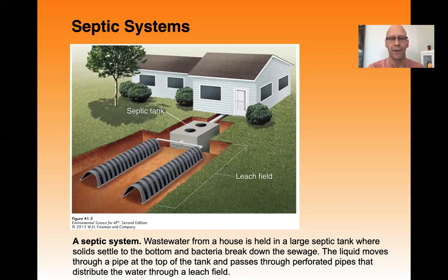And the bacteria that are in your soil are the consumers of any organic waste that's in your home sewage. And that bacteria can process that waste, and as that water infiltrates into the soil, eventually at some depth, you end up with just clean water. And so the soil itself is not only the filtering system, but also the system that consumes any harmful waste.